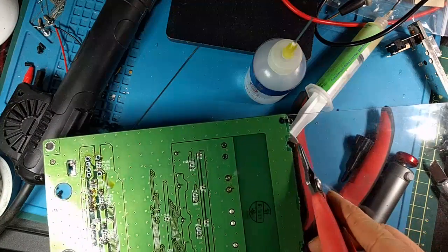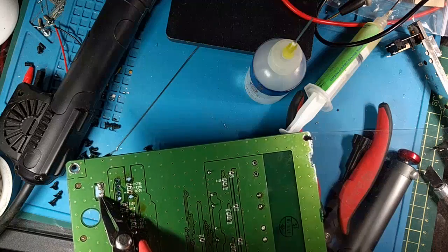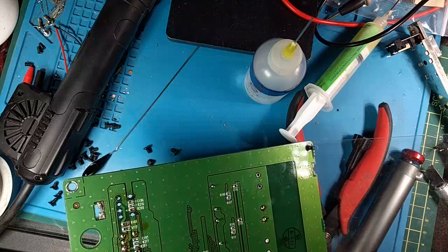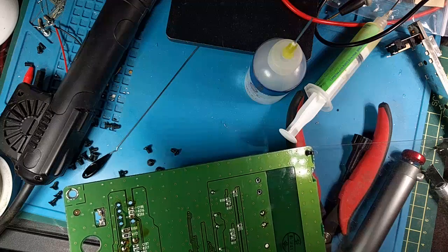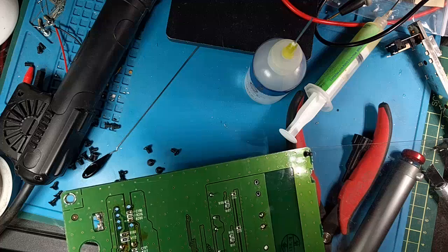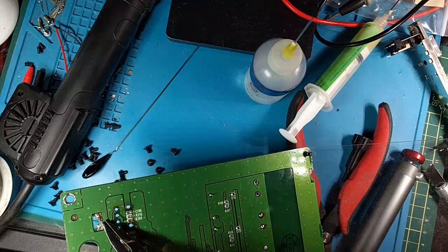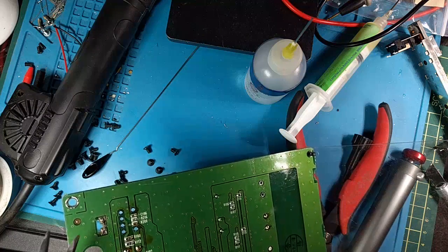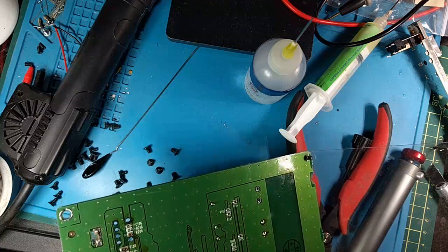And you got to push out the tabs on one side, and then the other side you've got to use a soldering iron, because it's a ground tab and it's not isolated. It's fully connected to this entire ground plane, which the copper will just suck up any heat you apply. So you've got to put direct heat with about 650 to 700 Fahrenheit of a soldering iron on there, and then use tweezers with the edge of the board to pull back each of those tabs.